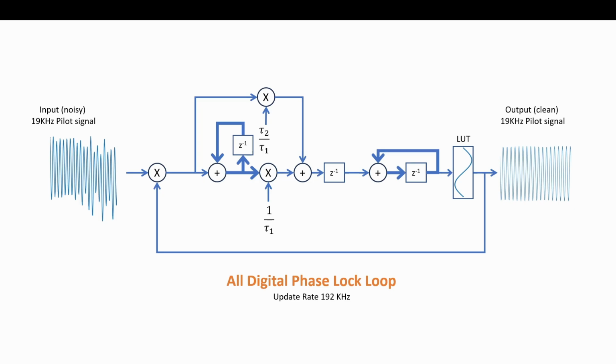There's a parasitic delay in our loop. We can't apply the next output until the next clock cycle, so it ends up being a parasitic delay that, if you don't include it in your model, you won't get the results that you're expecting. And then here's another accumulator, taking the output after a registered delay, in a particular implementation, for similar reasons. This is a numerically controlled oscillator, an NCO.